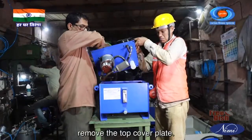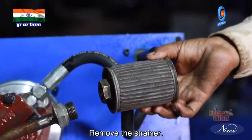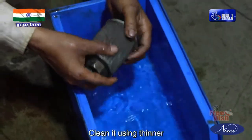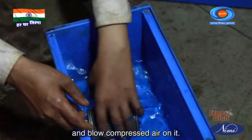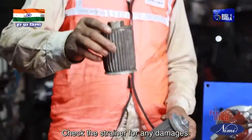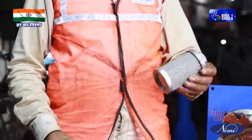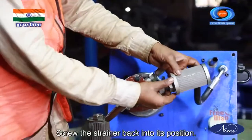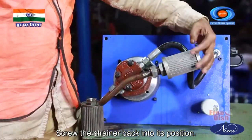Remove the top cover plate. Remove the strainer. Clean it using thinner and blow compressed air on it. Check the strainer for any damage. If any, replace it. Screw the strainer back into its position.